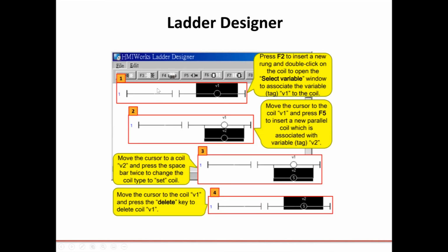Each rung in the ladder defines a variable or a function, and inputs and outputs on the left and right respectively can refer to physical I/O variables or virtual tags that deal with internal functions. The rungs in a ladder diagram are essentially a set of nested if-then-else functions that respond to input values, store and change variables, and trigger outputs.